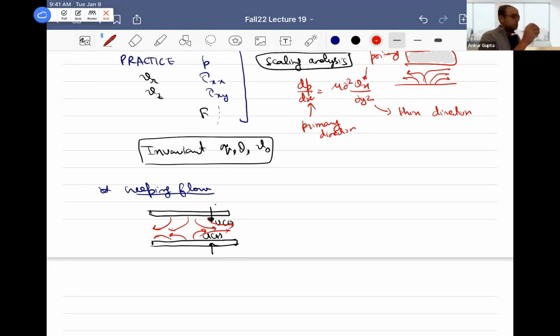Because Reynolds number was small, we could make it a pseudo steady problem. So it was a lubrication problem made pseudo steady by the low Reynolds number. So that's why this equation will still hold. This equation will still apply here, but we can still use a time dependent boundary condition because the lubrication was derived for a steady system. Okay, so it's almost like a similar idea.